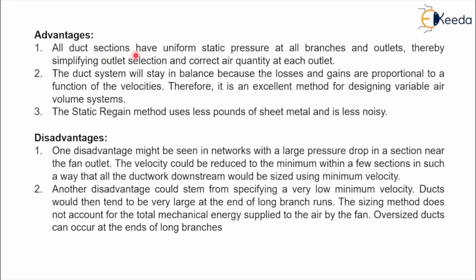All duct sections have uniform static pressure at all branches and outlets, therefore simplifying outlet selection and giving the correct air quantity at each outlet. I think you can understand that. That means we are giving the same or equal quantity at each outlet of the duct in a room.